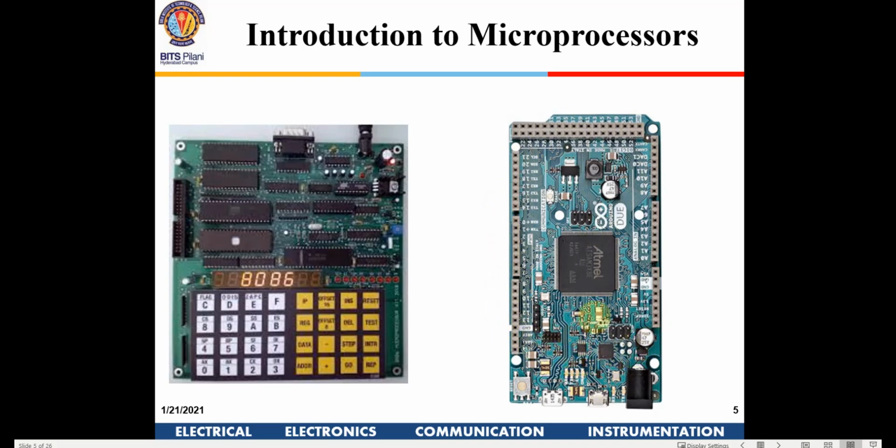There will be a small power supply regulator. So it has essentially all input output ports. You give inputs and you take the outputs from here itself, and you program the Arduino. The memory is within this chip itself. You are going to dump the program into this chip, and once you run it, you just have access to these input and output pins. Okay, whereas in a microprocessor, this is the chip, and everything is external to it.